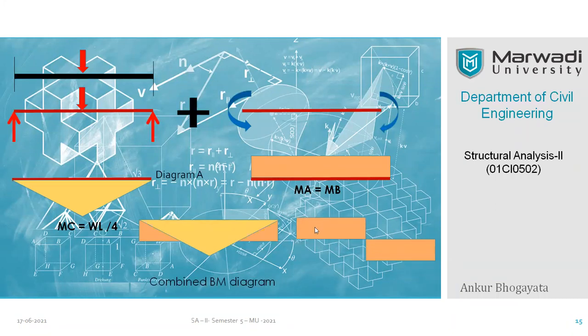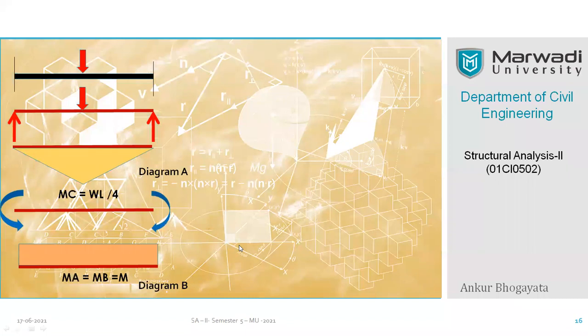Right? This is also a kind of shear force diagram which is based on this simply supported structure. Right? So there is no shear force as such on this beam, so there is no point in drawing the shear force diagram. So always, even for the fixed beam, the shear force diagram is as per the simply supported notion only. The only change in the diagram is the bending moment diagram. Right. So now this is the concept, but we need numerical values also.